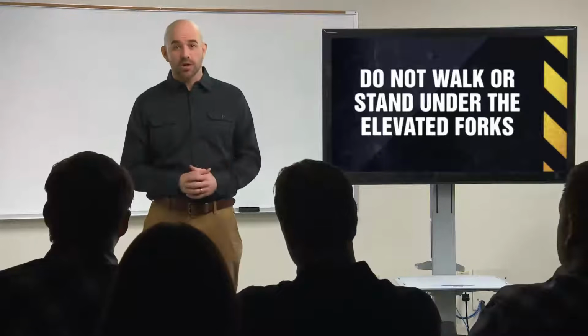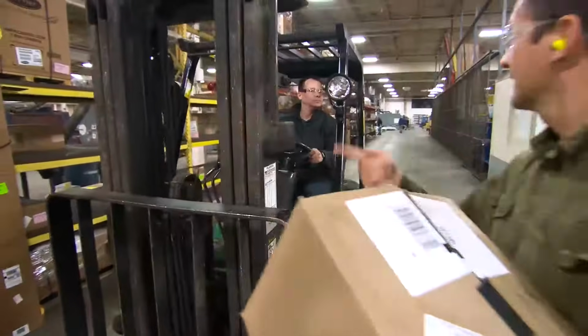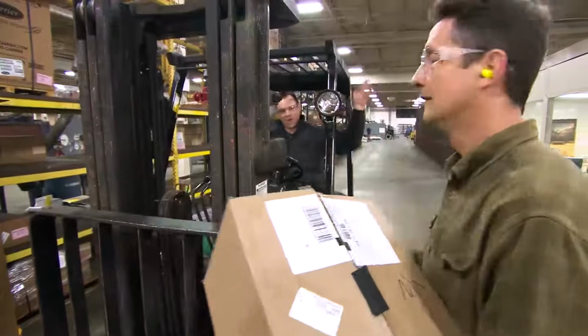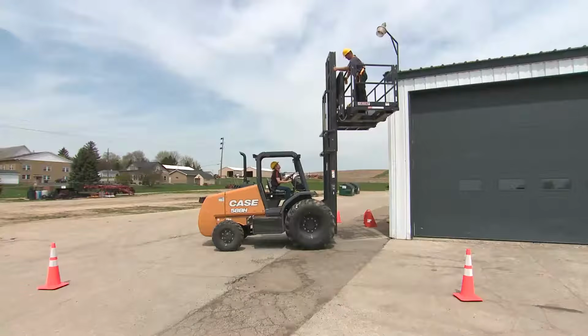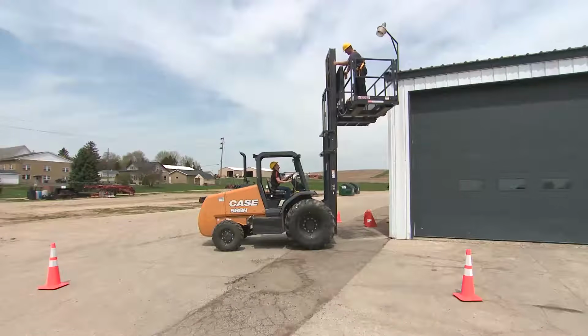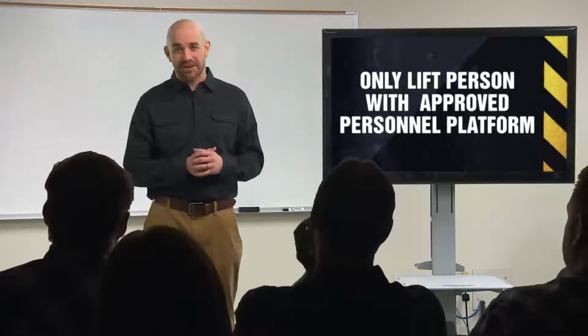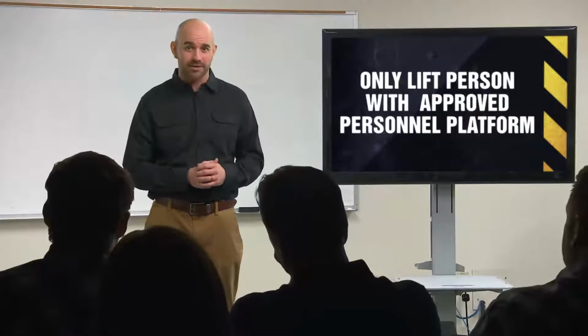Don't let anyone walk or stand under the elevated forks. Never carry passengers. And only lift another person using a forklift if the lift is equipped with a manufacturer-approved personnel platform. Never lift anyone standing on the forks or a pallet.